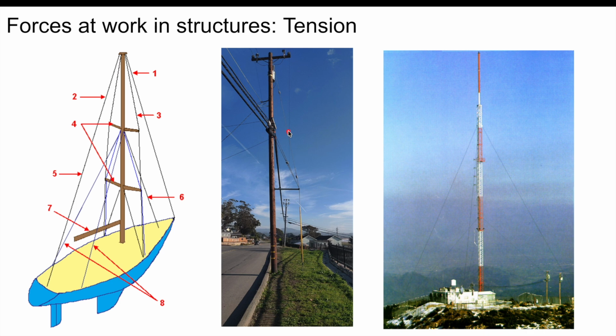And these are acting in opposition to forces that are pulling this telephone pole to the left. So the wires that are coming out of the telephone pole here need to be counteracted using these guy wires. Otherwise, this pole would tip over towards the left. And so that's what these are all about. They're counteracting these wires right here that are going off to the left.